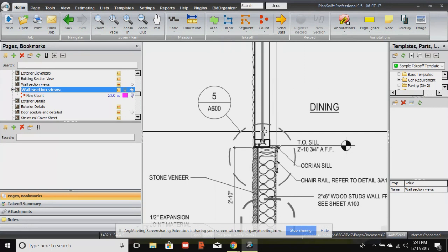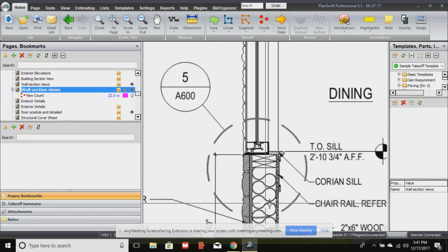From our section view, we got our height. Our blocking, our insulation, our wood, our framing types, our heights, all that from section view. Now, the architect's saying, well, you're not finished because there's something you need to know in this area, circle. Same concept applies. Image number 5, page A600, same concept applies.